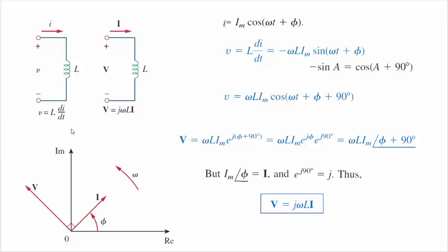That's sort of like Ohm's law, V equals IR, where now the linear constant is this inductance value, but instead of voltage and current being directly related through a linear constant L, it's related by the rate of change of current. In a way, it's a different form of Ohm's law, although it's not Ohm's law. It says the inductance relates the voltage and the rate of change of the current in the circuit.